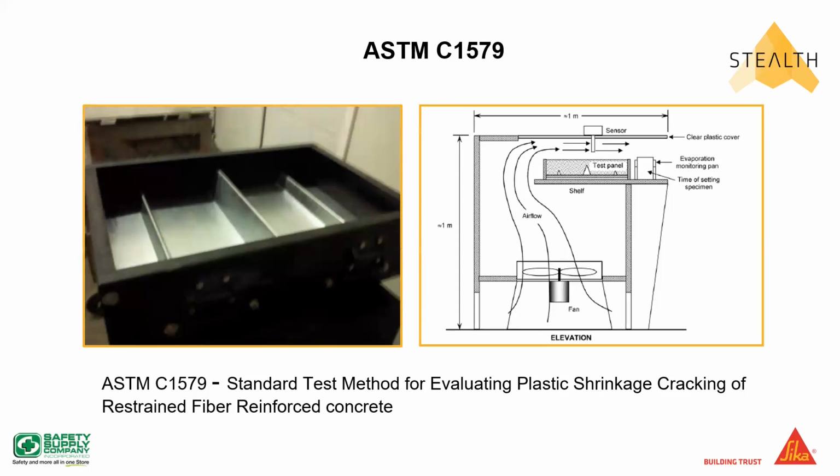As far as testing for the fibers, as far as the microfibers go, the standard test is ASTM C1579. The picture on the left shows the tray that we load the concrete in, the test specimen, and then on the right it shows you how it works, just simply blowing air. So what you're doing is drying the surface of the concrete faster than the concrete is curing within. That's where you get your plastic shrinkage cracks, your temperature cracks, and things like that. So that's the test.